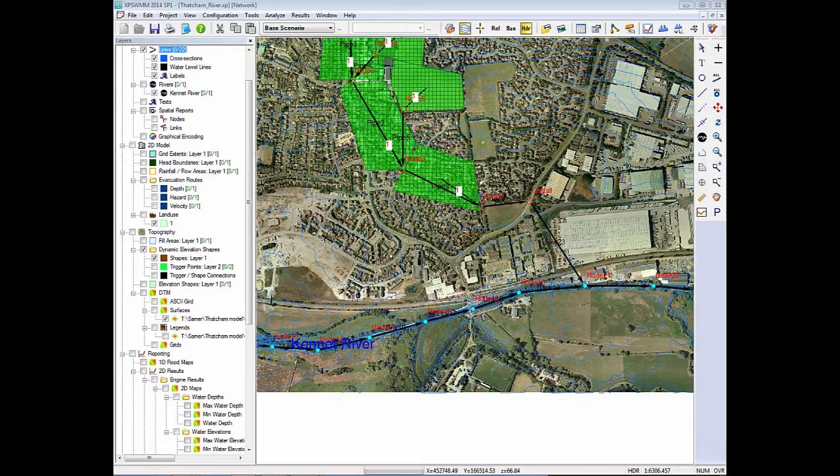Another way to mitigate the flood is having big storage areas. In some places, big storage areas should be considered to store the stormwater for some time while we're having the extreme event. And then we can feed it back slowly to our network. And these storage areas could be online storage or offline storage. Starting with the online storage,